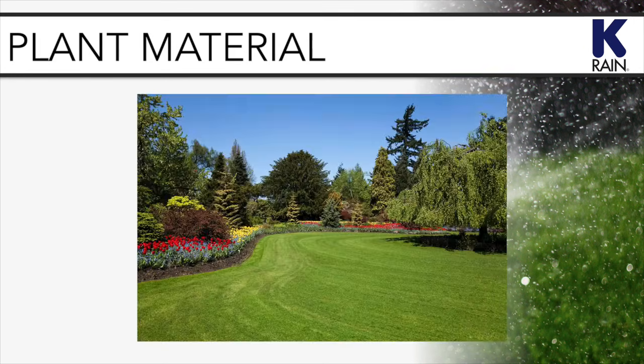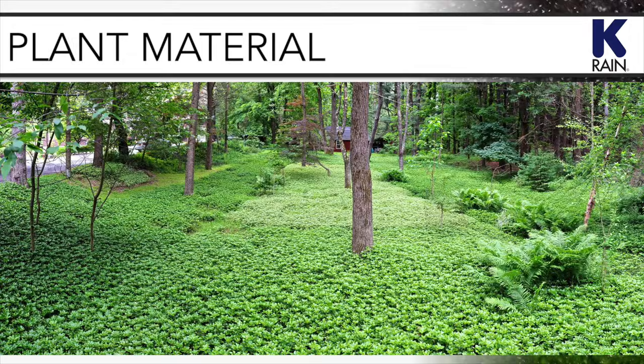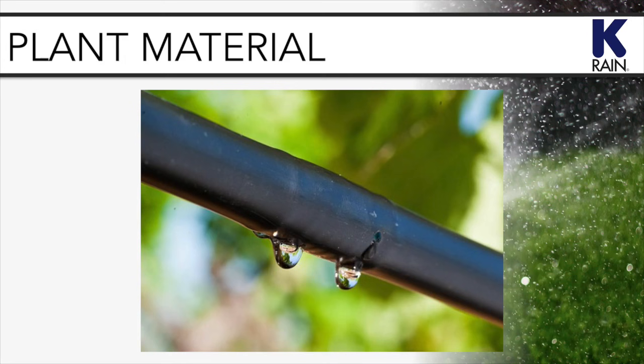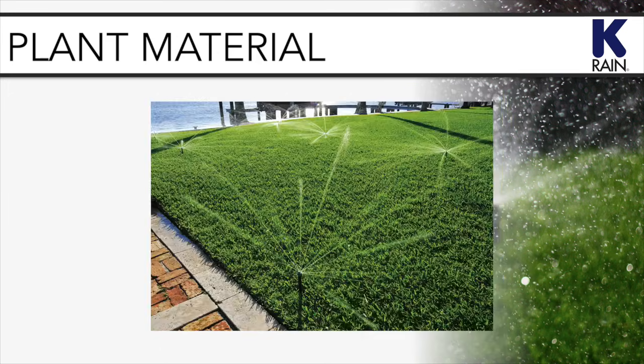High water usage plants like turf should be on different hydrozones than low water usage plants like ground cover or more sparsely planted shrubs. A point source strip system can provide different quantities of water to plants on a single zone, but most irrigation methods distribute water evenly over an entire watering area. Areas with different water requirements should be in separate hydrozones. This prevents a scenario where some plants are underwatered while others are overwatered.